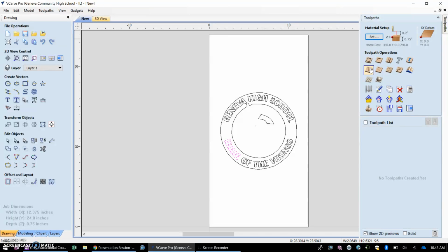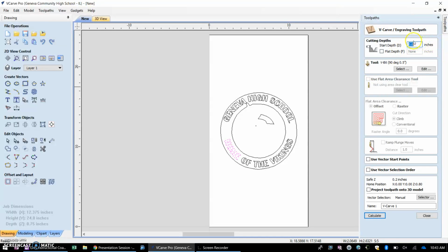So, when you look at the actual product that's created, it has that V-carve. It has that arc, those diagonal cuts kind of in the bevel areas. If that makes sense. So if I wanted to just take this home and make it a bevel cut for that, I would hit VCarve, engraving toolpath, and I go through the options. We want to start the depth at 0.